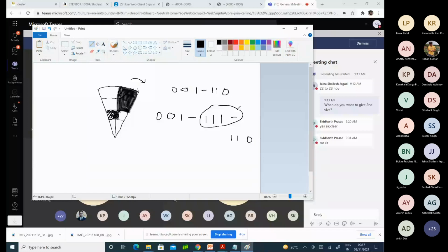So this may happen due to the construction process, and if this happens, always some other pattern will come which is not correct. We cannot perfectly avoid the construction mismatch or misalignment, but to avoid this problem, we have to go for binary to gray. In gray, there will be no chance, because there will always be one transition.